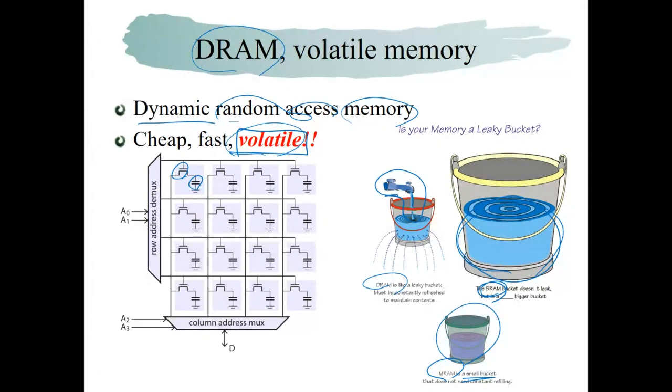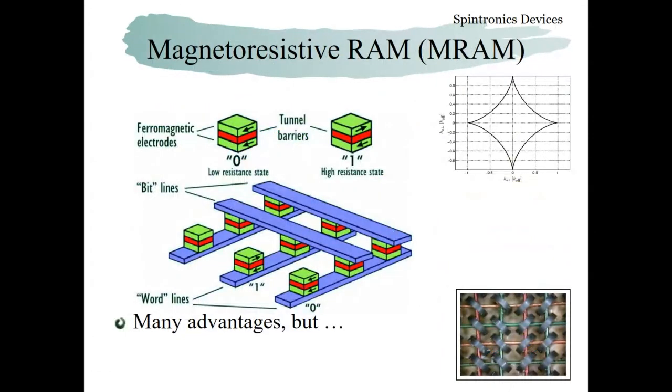So with this idea, people tried to make the MRAM structure, which I already mentioned in a previous class. I hope students can remember this astroid curve with the field-driven MRAM. If we make such an MTJ array with such lines, we can store the information in one free layer, and we can read out this information by the TMR.